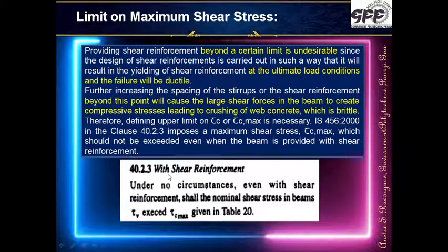It says that under no circumstances, whatever amount of shear reinforcement is provided, shall the nominal shear stress tau v, calculated as Vu upon Bd, exceed tau c max.